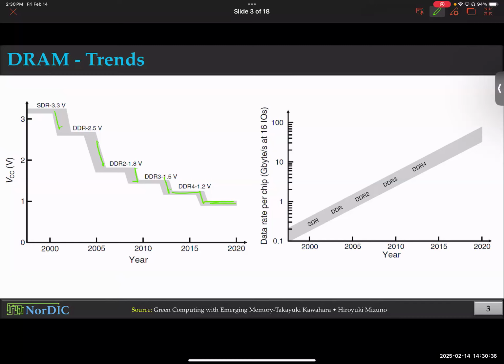Getting back to the same problem, there is a concept called overdrive, which determines the strength of the transistor. Overdrive voltage is nothing but VGS minus V threshold. That's your overdrive. Whatever gate voltage you provide versus whatever threshold voltage your transistor has. That's what determines your on current. That's what determines how much strength your transistor will have when it is operating.